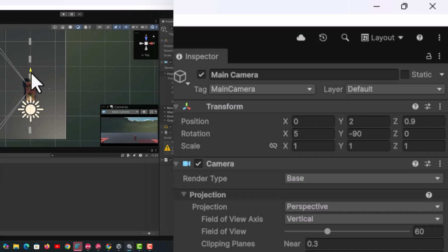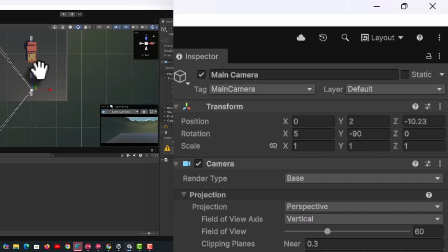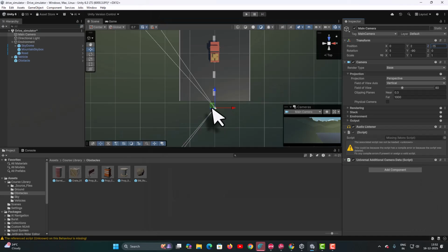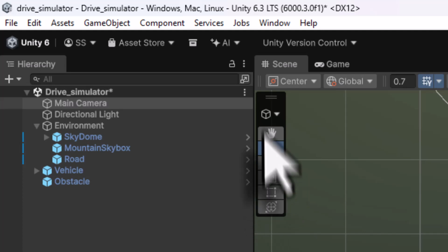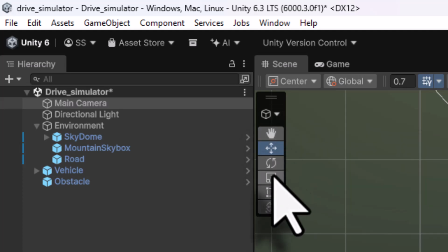See, as I move in the preview, you can see it. I will just move it with middle mouse click. I will pan it like this, move it by around minus 15. Now the camera is placed here, but only problem is the camera is directed towards my left. I want my camera to be rotated and it should see towards the top here. So to rotate the camera, I am going to move into this rotate tool. So in this panel, you have all these transform tools.